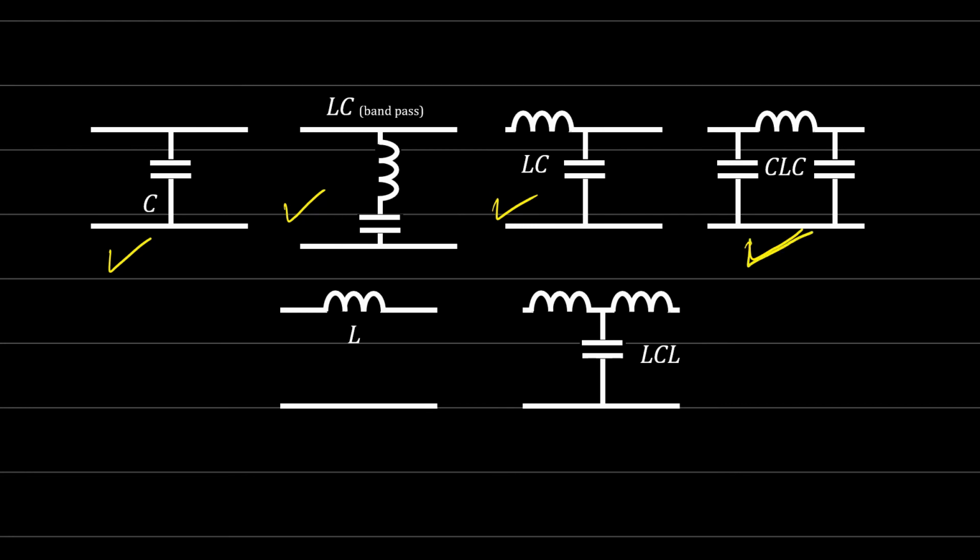Very good. Now, these can be considered for the standalone inverters when you have a load and you want to supply this load. For grid-connected inverters, usually we prefer to use a current source. We prefer to use an inductor at the output, okay? So before going to the grid, we need to make sure that we have an inductor before supplying the grid. So we can use an L filter like this. This L filter has poor voltage regulation and it's bulky and costly. If you try to increase the value of the inductor, you'll find this is a bulky inductor. The voltage regulation for this is not very good, and at the same time it's bulky and costly.